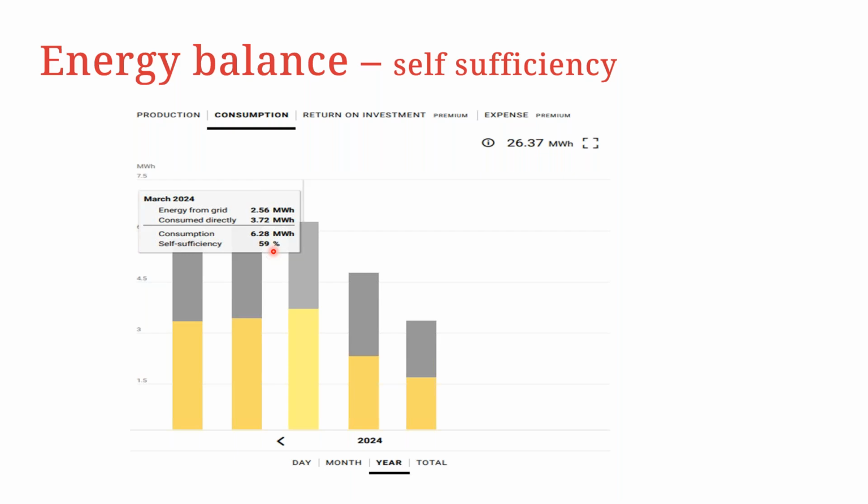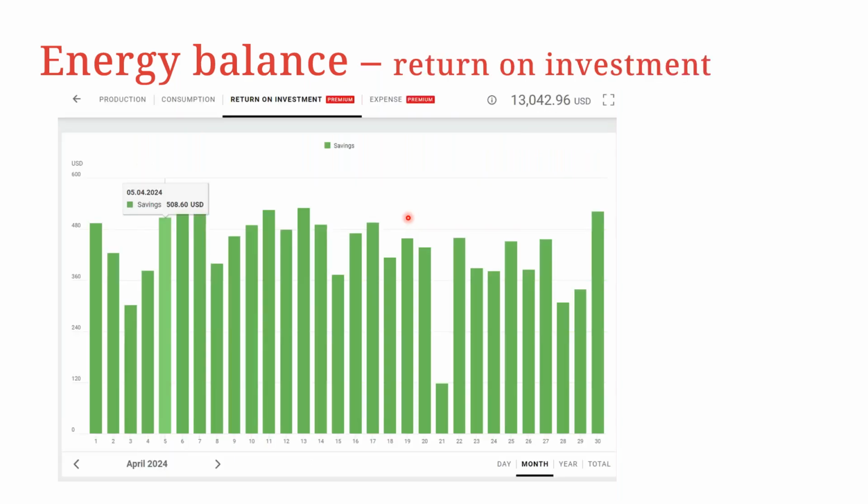And therefore, you can answer very easily when you're doing your energy analysis and energy balance, checking what are the figures in SolarWeb, and you can advise your customer how then to improve these figures. So in terms of the return on investment, you can also check quickly from SolarWeb, and this is why it is important when you're commissioning the system, you enter the actual cost of energy for your particular region.